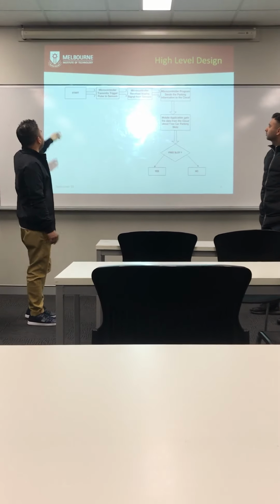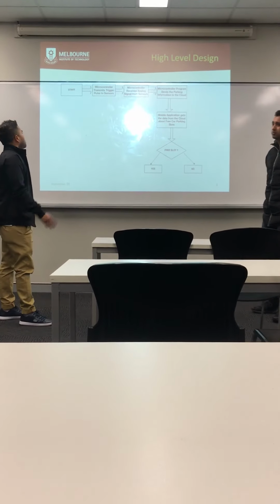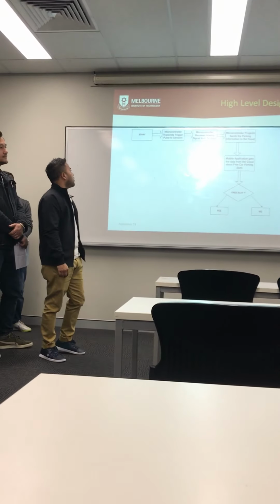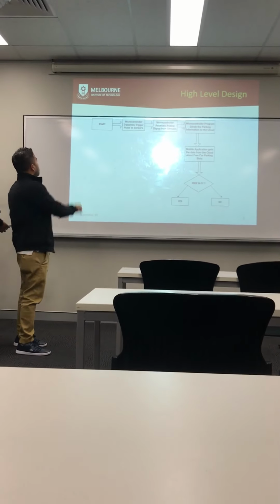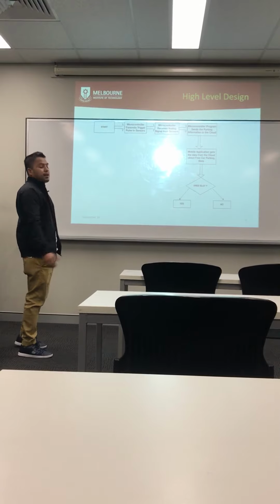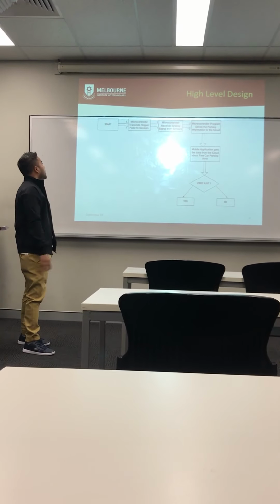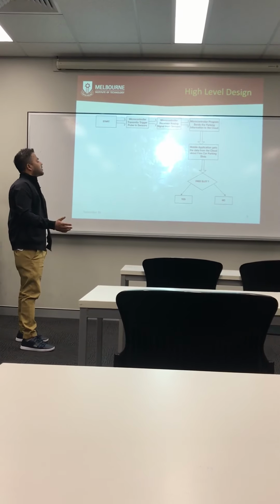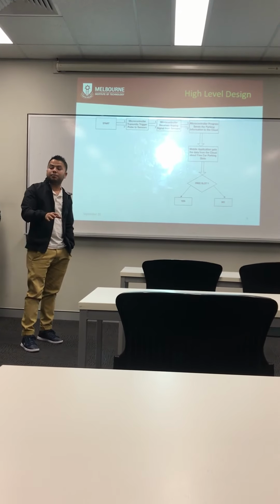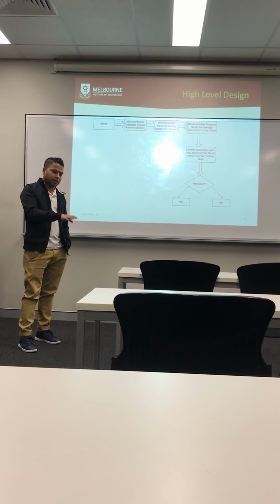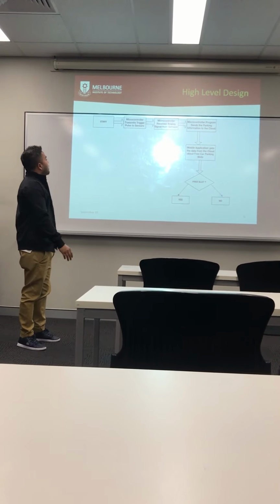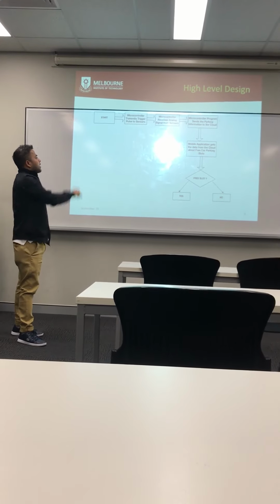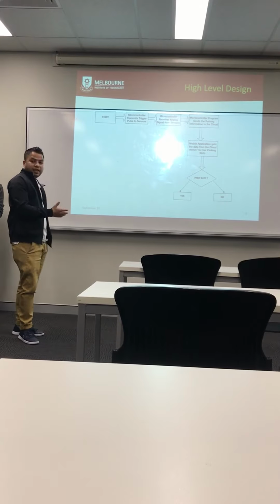So in the starting, when the vehicle enters the parking slot, there is a system which uses a microcontroller chip like Arduino. Whenever the vehicle enters the area, the system gets started, and the microcontroller triggers a pulse to the sensors. And these sensors, like ultrasonic sensors, will detect the object, like there is a car or something there, and then the microcontroller receives analog signals from the sensors.